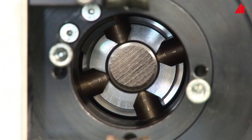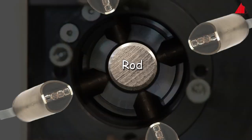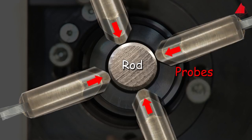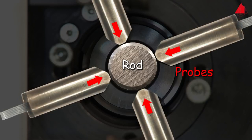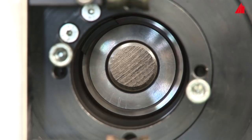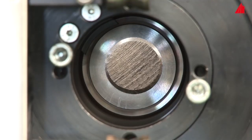A look into the interior of the machine shows the rod in the centre. Here, the rod is not only scanned by just 1 probe, but in fact by 4. And each of the probes is equipped not only with a single coil, but with several ones. The probes are positioned radially at a small distance from the rod surface. During operation, they rotate around the rod at high speed. Meanwhile, the rod moves through the machine in longitudinal direction.